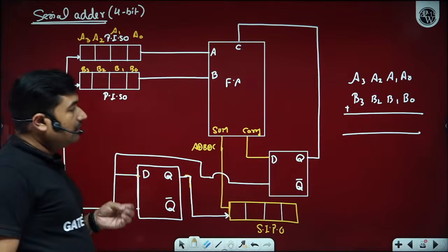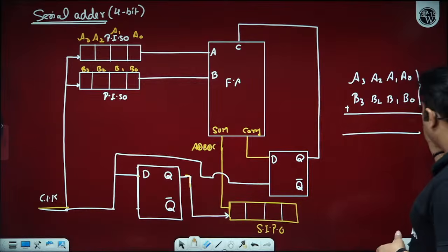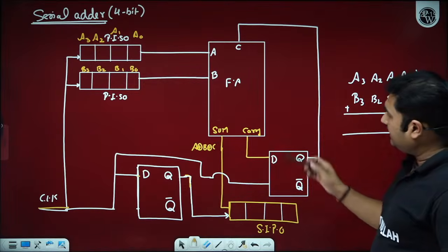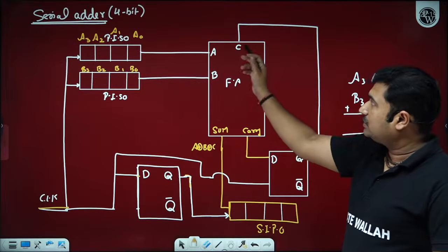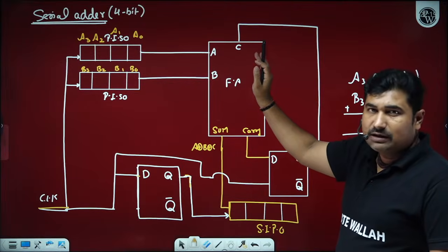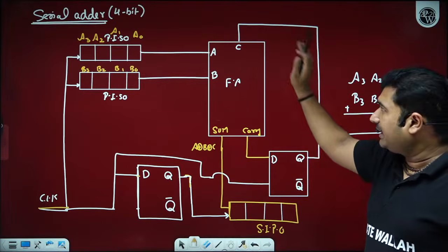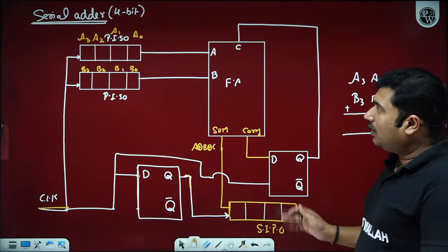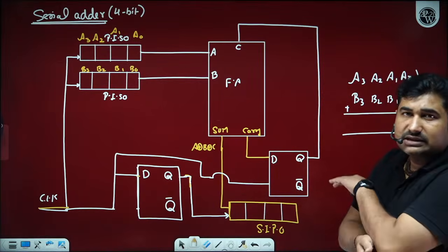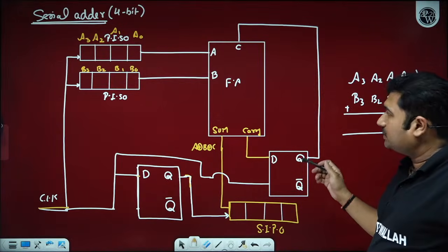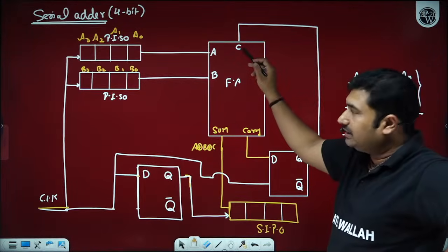Please observe. At the time the addition starts, A0, B0 and the initial carry C0 are there onto the full adder, before applying any clock pulse. Before the addition gets started, we have A, B, C all 0; all the registers and full adders are reset, and the outputs of the full adders are reset. So the initial carry 0 will come here, C0.